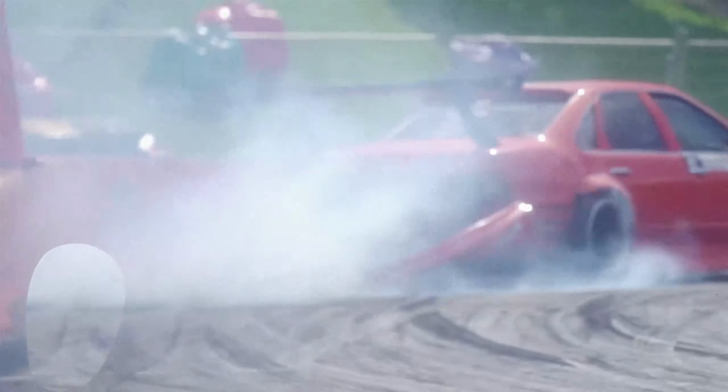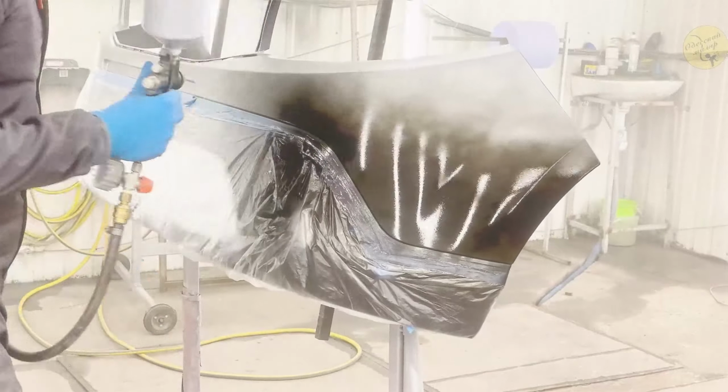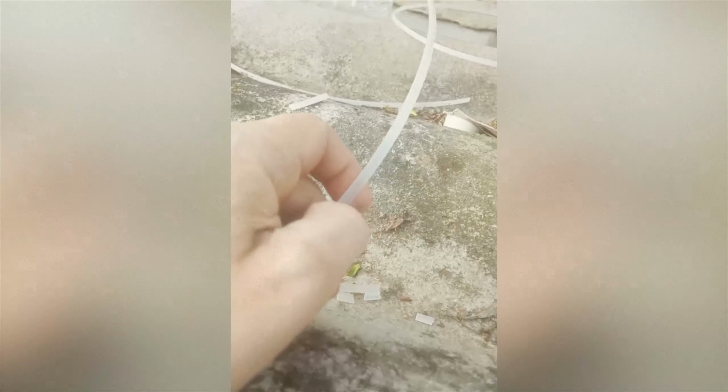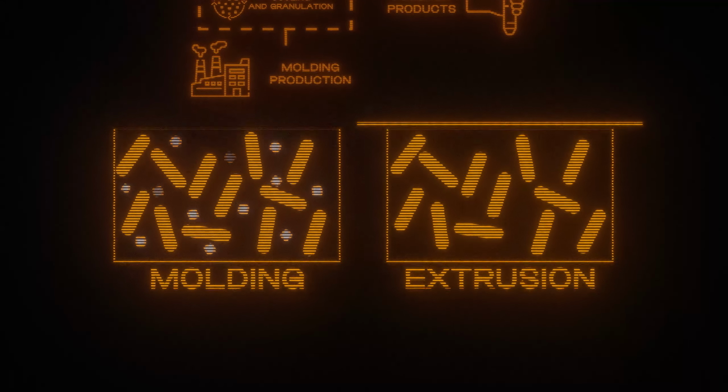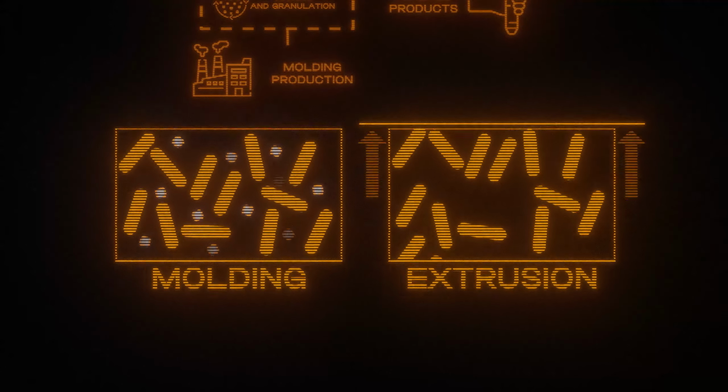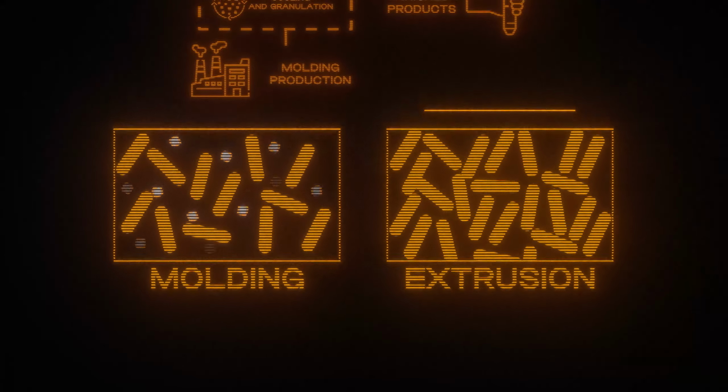Extruded rods, due to their poor composition, deteriorate in the sun in a matter of months. Such rods are brittle, rough, fragile, and do not hold paint. Trying to degrease and paint such a rod is like trying to degrease and paint a paraffin candle. Pure polypropylene is essentially grease. Paraffins will constantly rise to the surface and cause layers of paint to peel off, no matter how many times you degrease it.